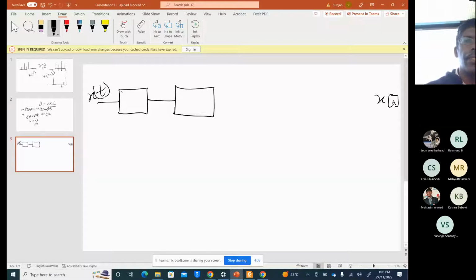So it's kind of a switch. And it says take the signal, and Fs has to be greater than or equal to 2 times F max. So what we have to do is remove anything higher than Fs by 2. That means we need an anti-aliasing filter with a cutoff frequency of Fs by 2. Then we have the sample and hold.